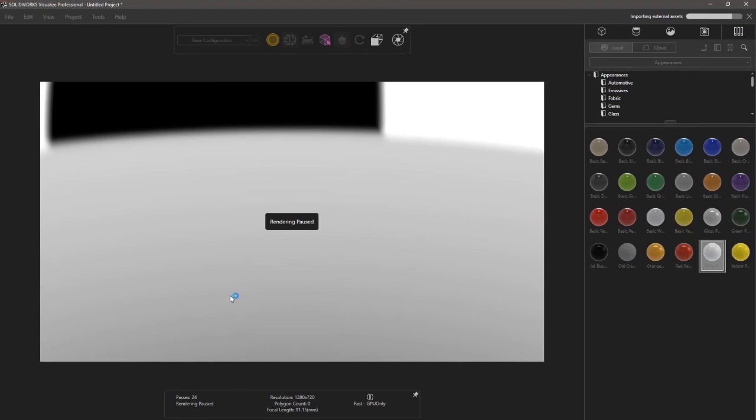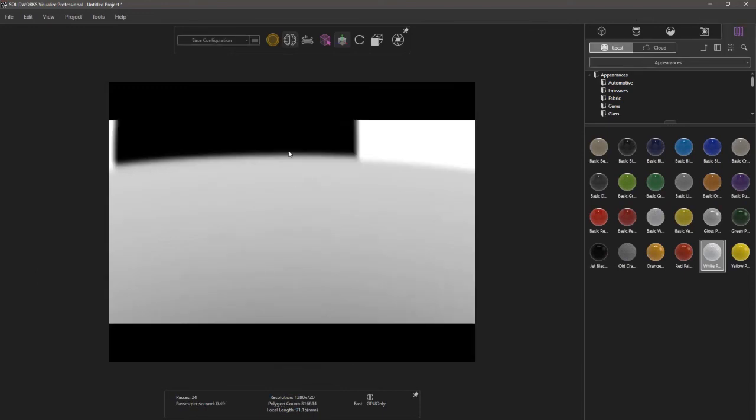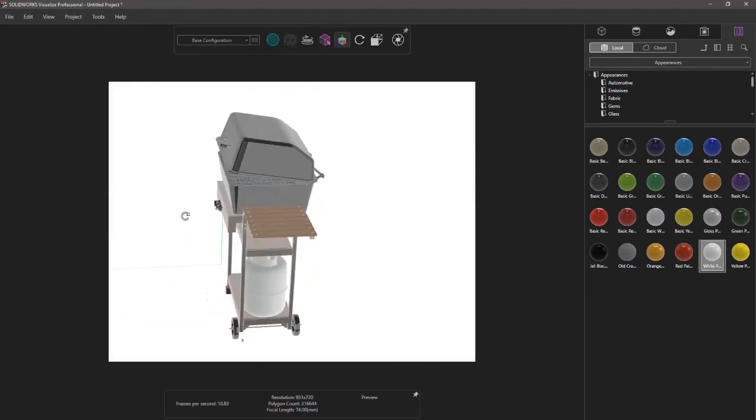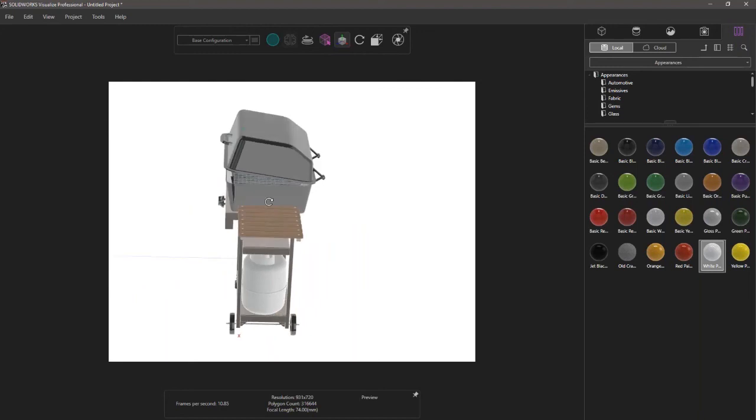So I highly advise against using retain structure. It's tempting because it keeps the feature tree the same essentially. It can be nice on a small example if your system can handle it, but odds are your general performance, just like rotating the screen around, even in preview mode, with retain structure on, is going to be quite a bit worse. And I realize it probably doesn't come across on the GoToMeeting, but when I'm rotating this, it's much less smooth than it was with the other import methods.